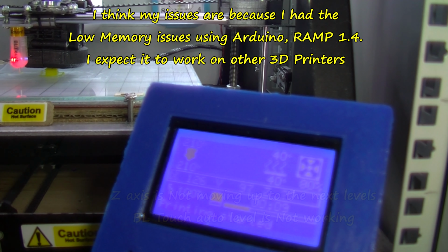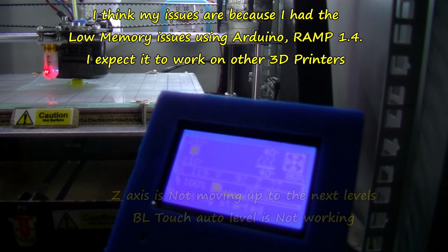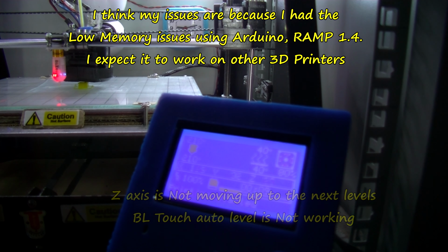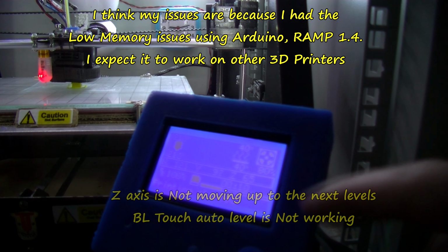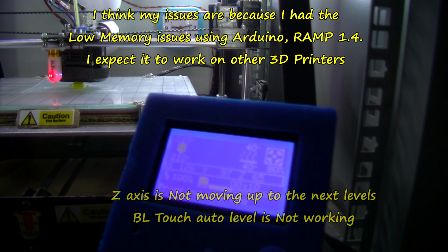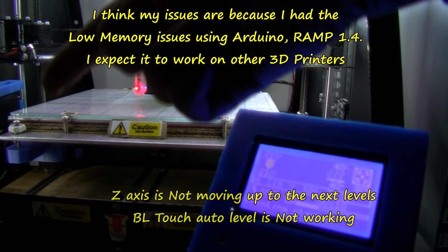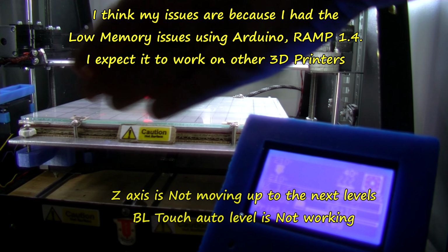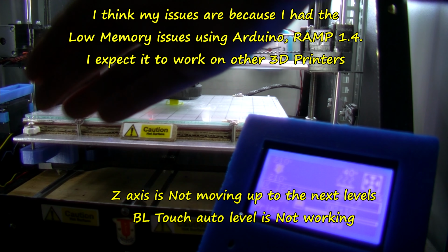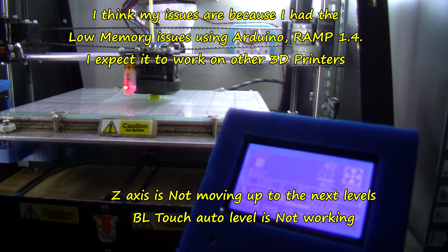Let's turn off all the lights so it's coming up with question marks for Z. That's like an unknown position because it hasn't homed. It didn't home when it went over to the left. It went over to the left, the bed went right far back and it came to this corner, but it did not home down on a Z position.